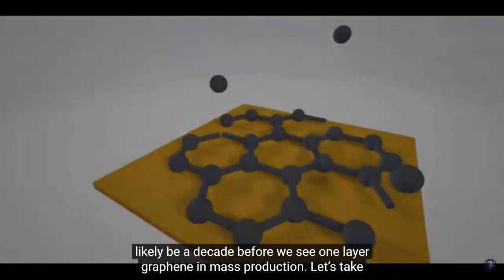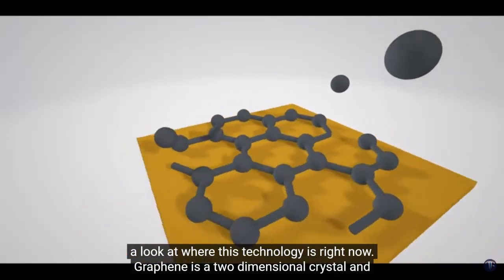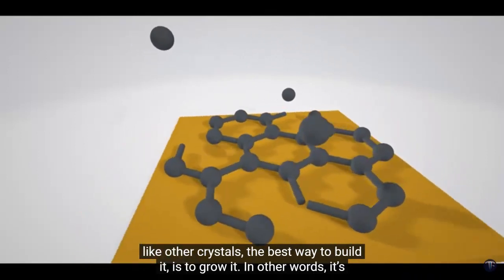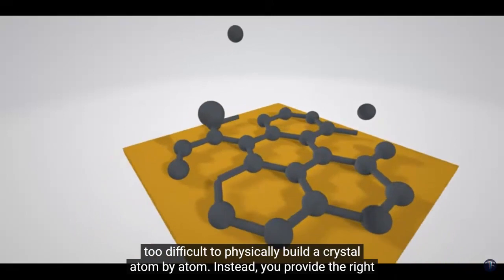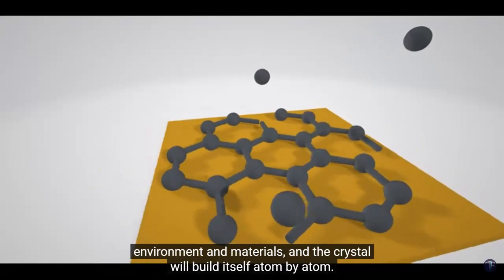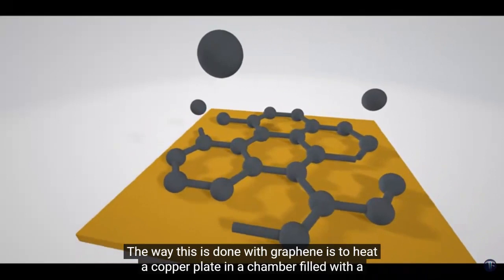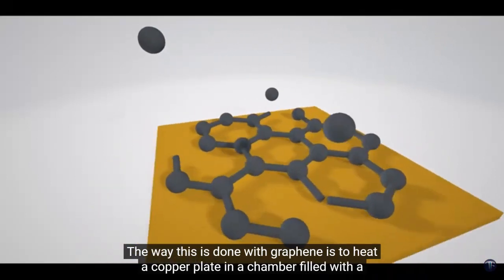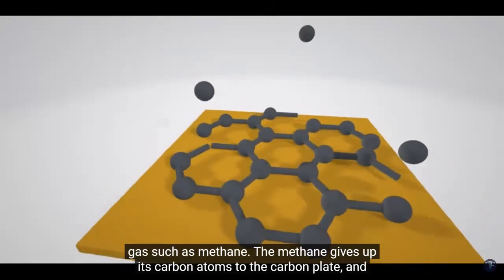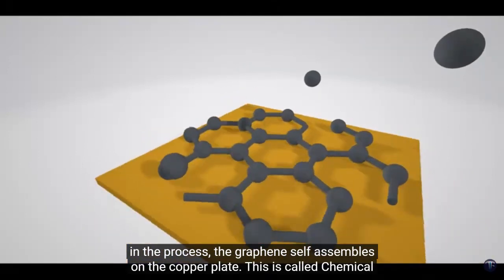Graphene is a 2-dimensional crystal, and like other crystals, the best way to build it is to grow it. In other words, it's too difficult to physically build a crystal atom by atom. Instead, you provide the right environment and materials, and the crystal will build itself, atom by atom. The way this is done with graphene is to heat a copper plate in a chamber filled with gas, such as methane. The methane gives up its carbon atoms to the copper plate, and in the process, the graphene self-assembles on the copper plate. This is called chemical vapor deposition, or CVD, and that's the easy part.